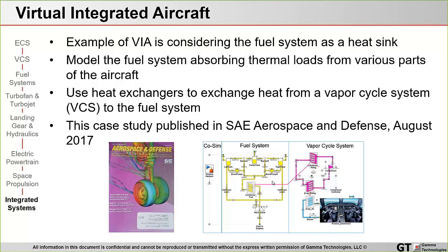In this model, it's combining both the thermal behavior of the electronics itself, the 2-phase behavior of the vapor cycle system, and then the single-phase fuel hydraulic system. And then there's also the ability to co-simulate with Simulink, as you can see in this example, or you could also think of using existing homegrown tools to do this as well, where you're controlling different aspects of the model with an external code. Now this study, if you want more details about it, was published in SAE magazine back in 2017.